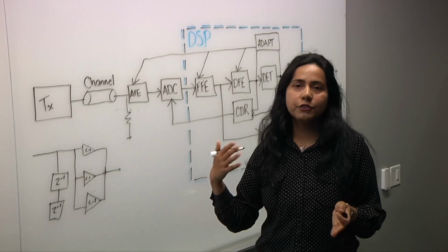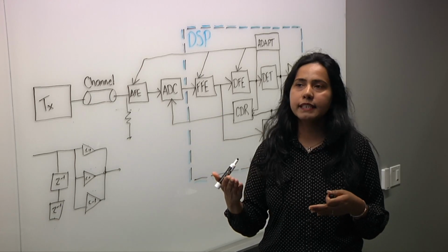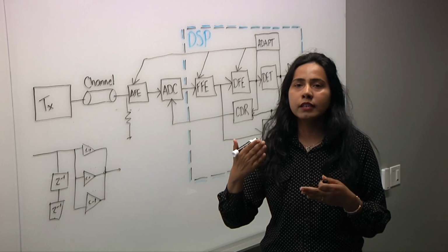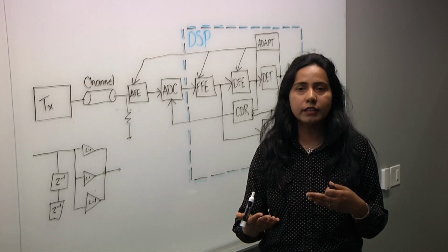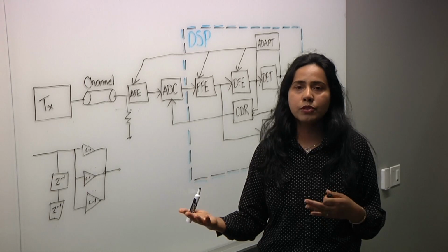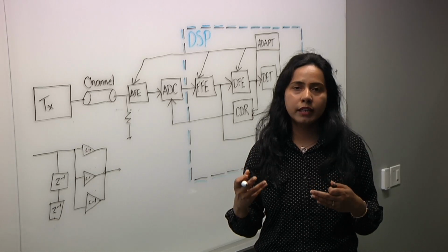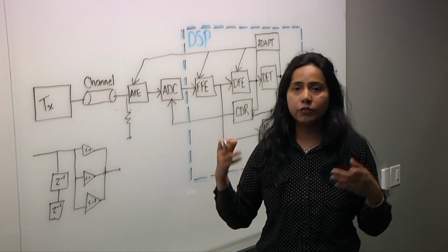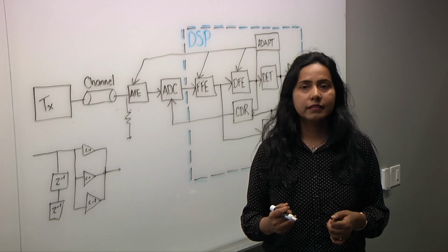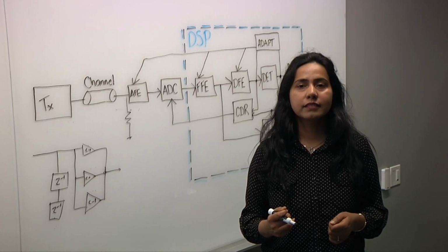Correct. So previously it was all in the analog domain. Now we are moving to the digital domain. The benefit is that it's very hard to fine tune these analog circuits with PVTs, right? But with digital, with shrinking process nodes, you can optimize it further with the process technologies available, as well as the EDA tools, which can optimize the power, area, performance, as well as latency of the digital circuit. Because a lot of these designs are also multi-die, you've got a lot of different pieces coming in. You now can develop this at whatever process node makes sense too, right, and integrate it into a multi-die or chiplet type of approach. Correct.